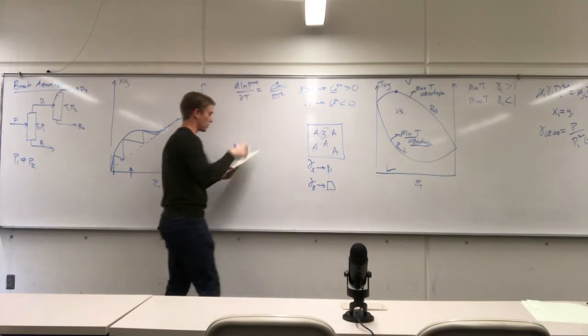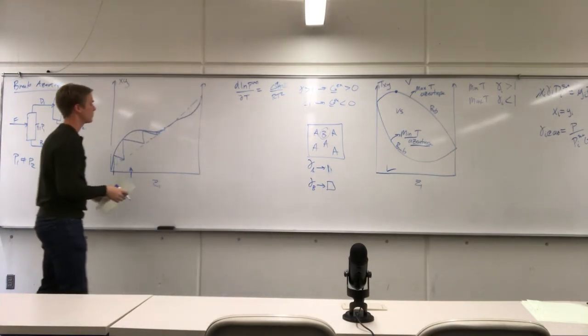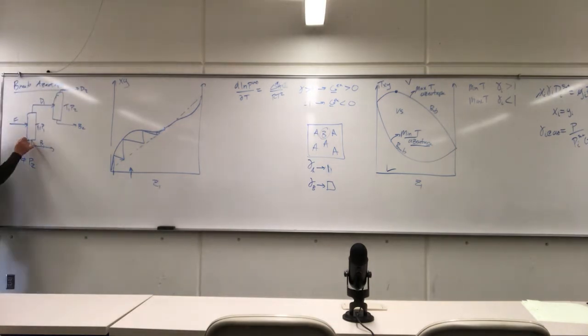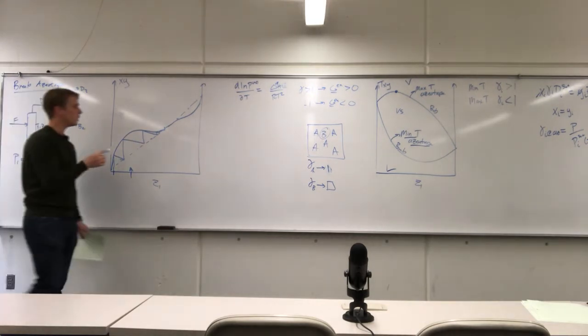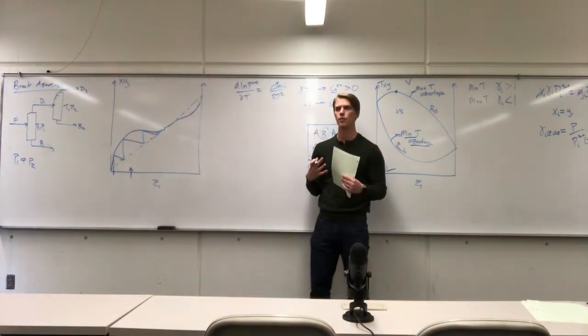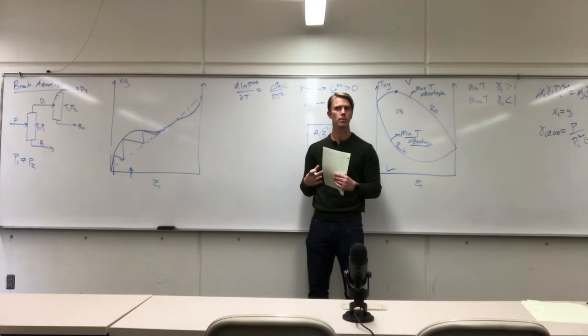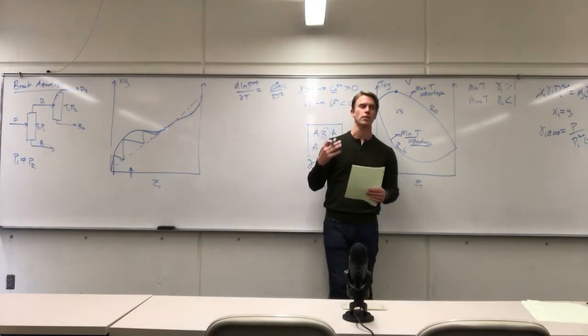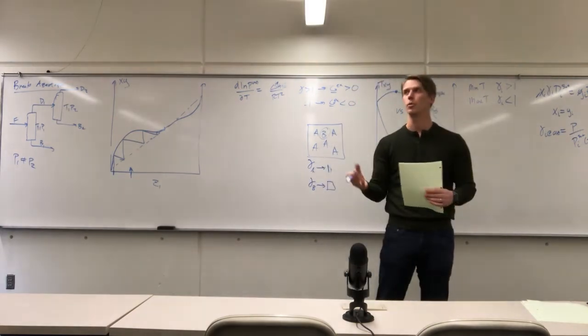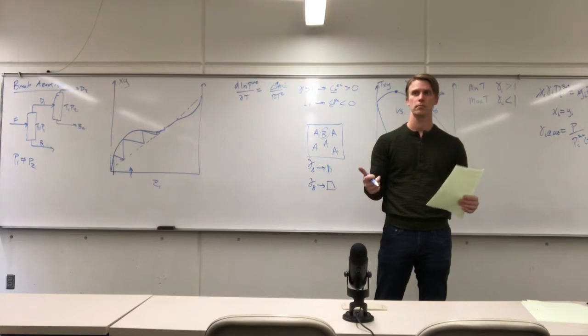In this case, this is the Clausius-Clapeyron equation, so we're assuming ideal gas behavior. What this is doing is, by varying the pressure of your distillation column 1 to your distillation column 2, we're effectively changing the temperature of operation of those distillation columns, right? Because, of course, temperature and pressure are linked to vapor equilibrium. If I change the pressure, I have to change the temperature. You can boil water by lowering its pressure or heating it up. Everyone's in agreement?